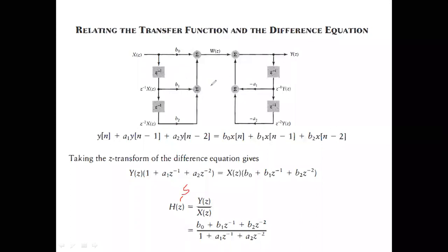Similarly here, when you have the difference equation, you can see this is something similar. X of n, x of n minus 1, x of n minus 2, and y of n. This is a feedback, y of n minus 1 multiplied by a1, y of n minus 2 multiplied by a2.